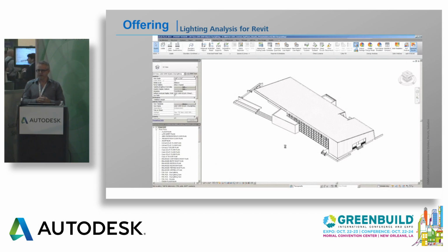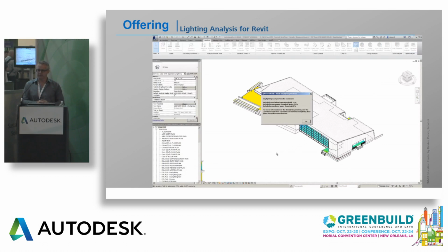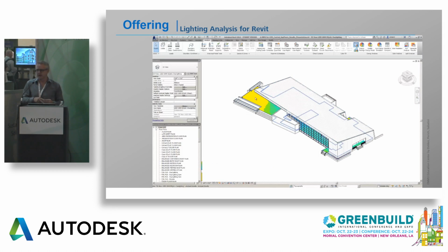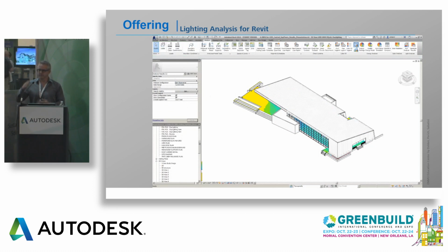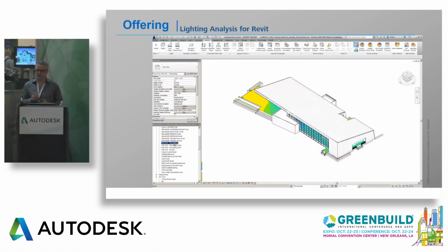Those are normally used by architects for labeling, space planning and takeoffs. When we run the model the first time, we assume that all rooms are occupied, and then after the analysis, you can go in and uncheck the rooms that are not occupied. Also on the schedule, you can choose whether a room has automated shades or not, so you can ignore the above the high threshold.